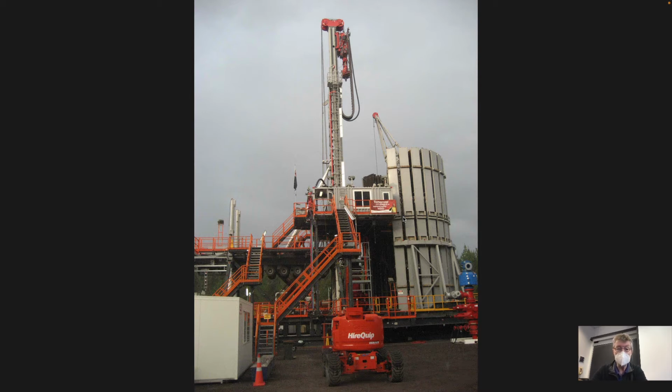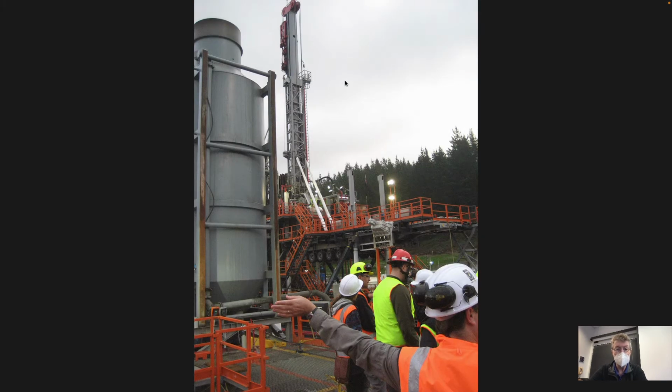So this just happens to be a drill rig, a geothermal drill rig. This is the mast. The drill pipe goes into the mast. This is a carousel. In each of these cassettes, there's a piece of drill pipe. Steel, maybe 20 feet long, I'm guessing, maybe 6 meters, which would be 20 feet, and maybe a few inches in diameter, which connects to a drill bit, which goes down the hole, and is just pulled out of these individual cassettes, raised up into the mast, and then pushed down and then drilled. We'll talk about that in due course.